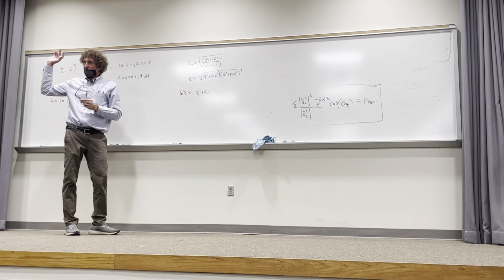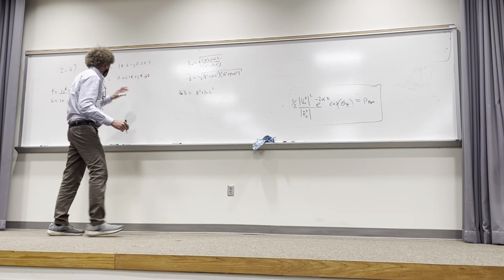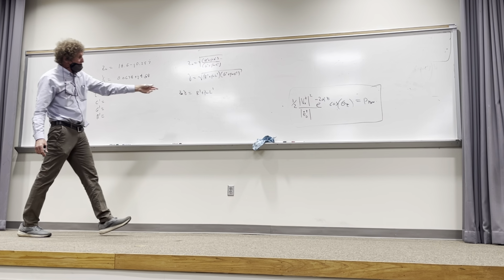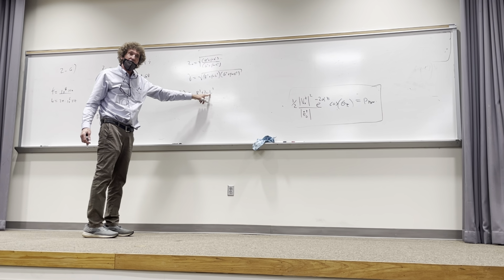How many see that? All right, so now I have this. You'll notice I can easily multiply these with calculators or computers, right? I can easily do that. So the real part is just R, and the imaginary part is this, where I can figure out L straightforward. Can I, class? By what? Dividing the imaginary value by omega, correct?